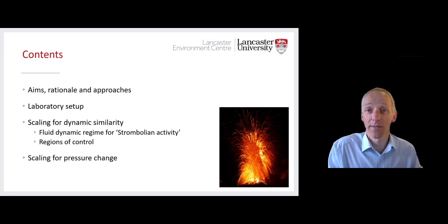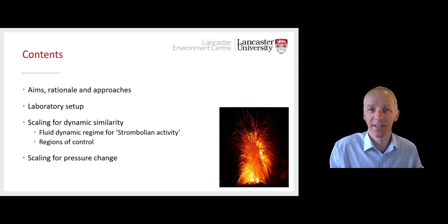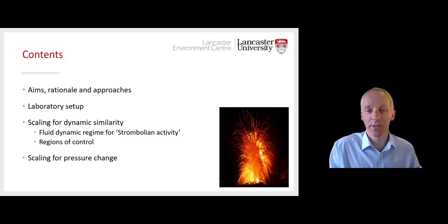In particular, we'll consider the relevance of matching fluid dynamic regimes rather than trying to precisely replicate particular values of the dimensionless numbers that are used in scaling. Finally, we'll consider the additional challenges that are driven by pressure changes, which are not considered within the conventional dimensionless analysis. In the volcanic system, these pressure changes result in substantial near-surface gas expansion. The rapidly changing dynamics involved underpin the activity that we observe at the surface. Thus, we would want to replicate these in our model because we're trying to represent the important near-surface processes.